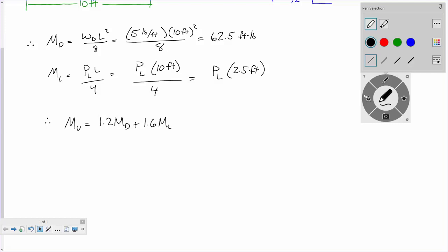Yes, sir. It doesn't state specifically in here, are there any assumptions, that we just don't have to take into account the weight of the beam? That's another good point. And I'll say this: unless stated otherwise, you probably want to at least consider it. But where it is concrete, we weren't provided with a self-weight, like a unit weight of concrete. You can assume something like 150, that's a common assumption, but it is that, an assumption. So,